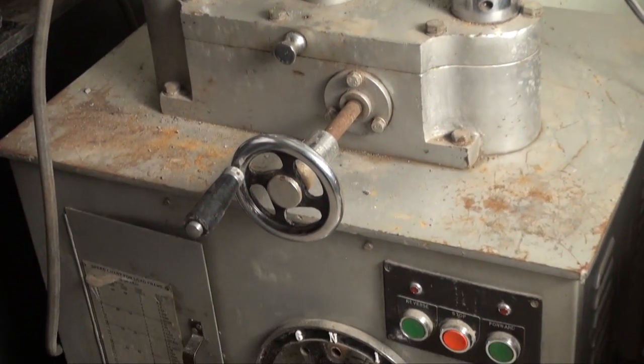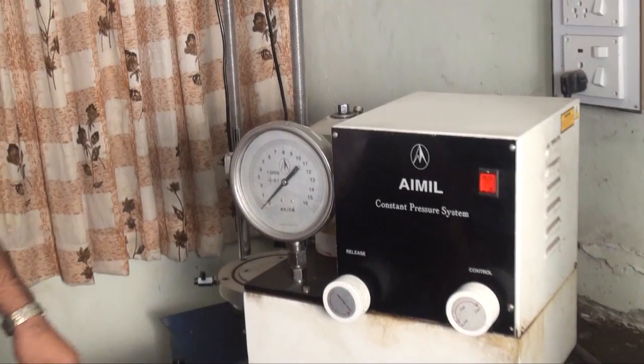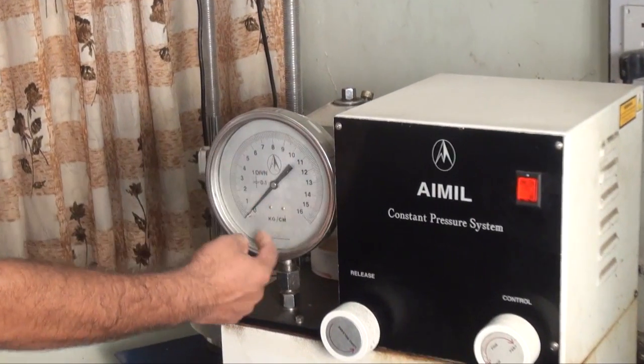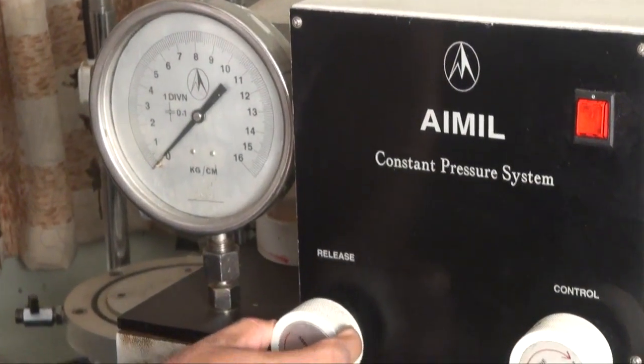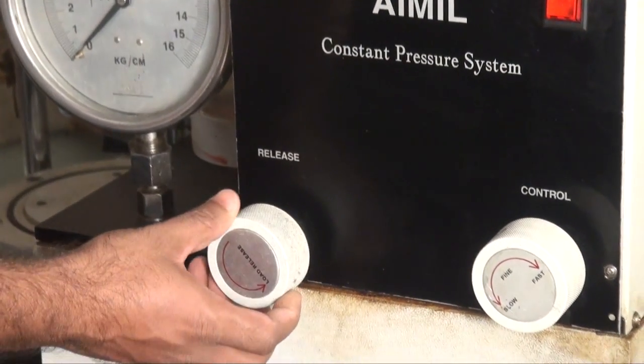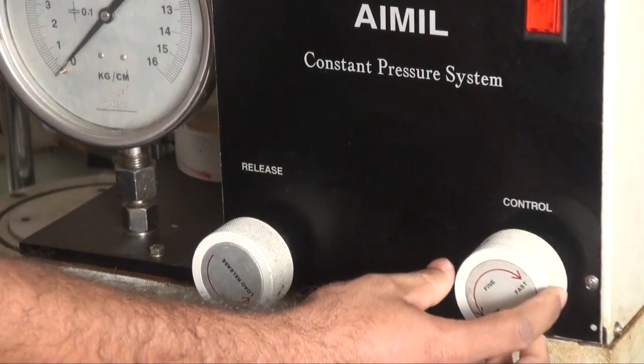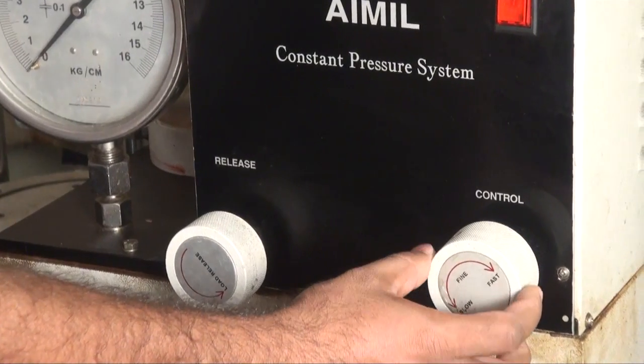It consists of pushing a 4-blade vane in a soil and rotating it in a cylindrical surface in a soil failed by shear. A torque required to cause this failure is measured and converted to a unit shearing resistance of the surface. All the parameters like deviator stress, strain, pore pressure are being measured while the tests are going on. And the procedure is not as easy as you think it is. But trust me, it is a very beneficial test.